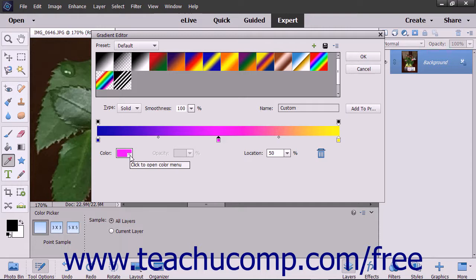To change the position of a color stop in the gradient, click and drag the color stop left or right to slide it to a new location on the color stops bar. Also note that when you click a color stop, you will see a small gray diamond appear. That is the color midpoint, which determines where the color changes between the adjacent color stops in the color stops bar. You can also click and drag these color midpoint diamonds to new locations on the color stops bar to change where the colors start to shift between the two colors.